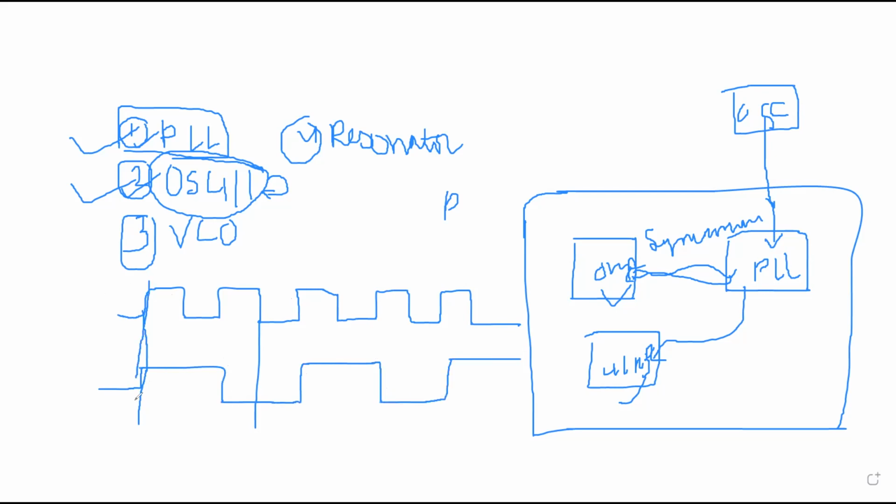If we see the phase difference at the posedge, we see that there is a phase difference of 0, so we say the clocks are synchronous clocks. So if the source of the clocks is a single PLL or a single clock source, we say the clocks are synchronous, or they should have a common phase difference.